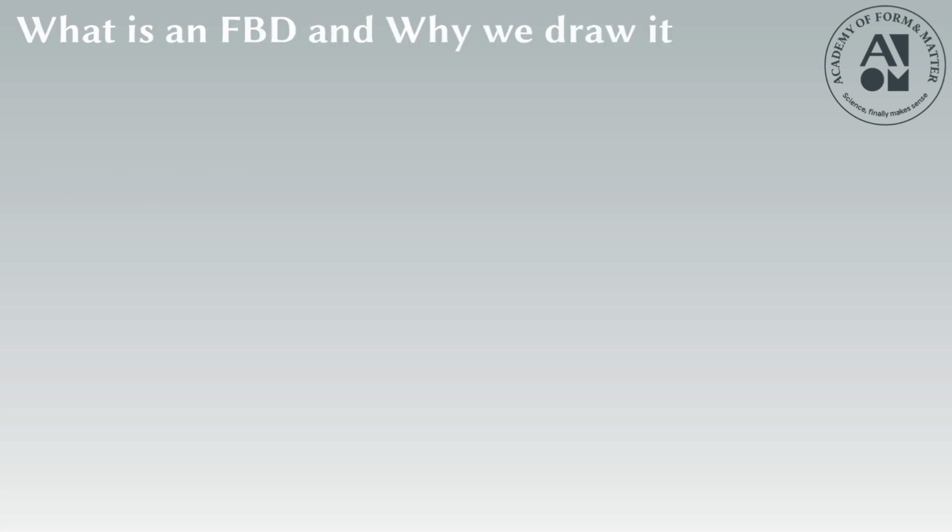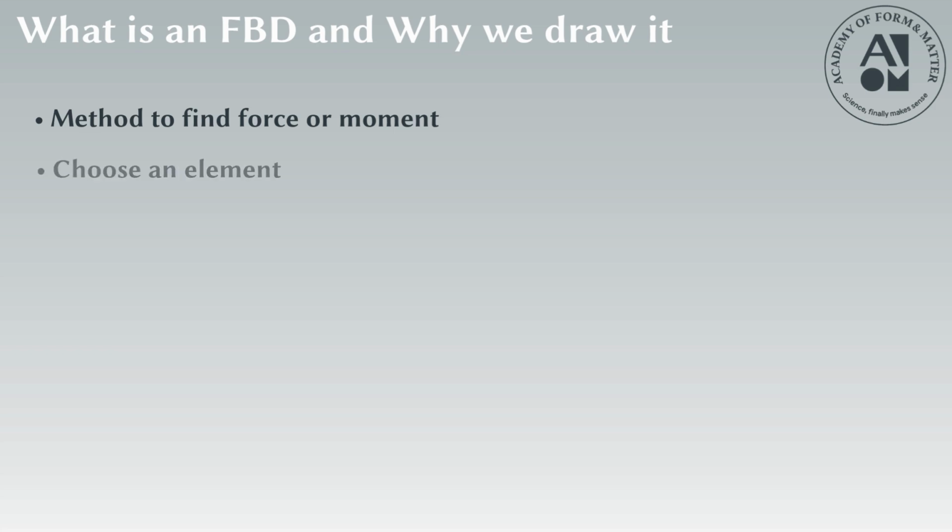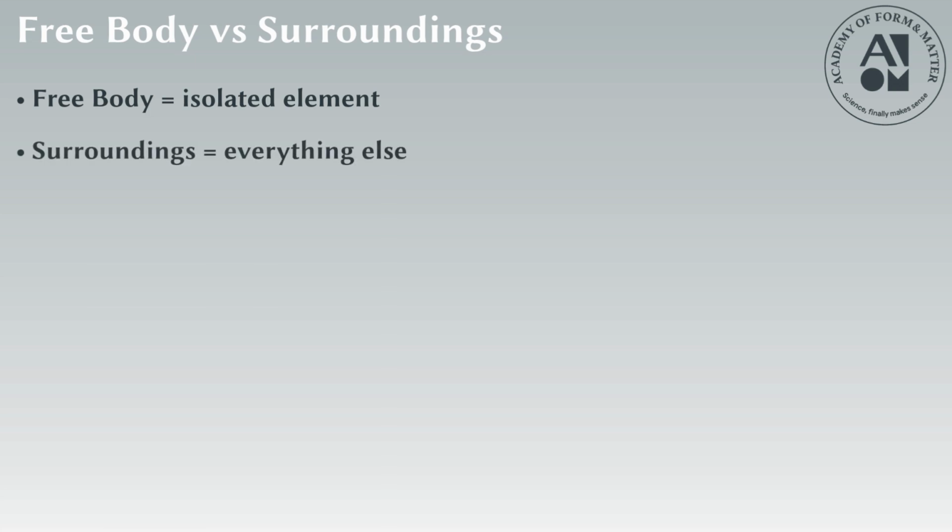A free body diagram, or FBD, is the simplest way to reveal the forces and moments acting on an object. The goal of an FBD is to reveal the forces and moments we want to determine. You take a real element, a beam, a column, or even yourself, and you mentally detach it from everything touching it. That isolated element is the free body. Everything you removed is the surroundings.